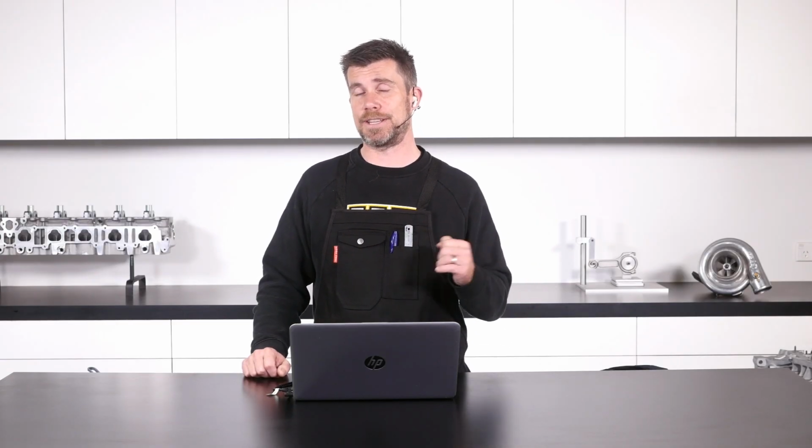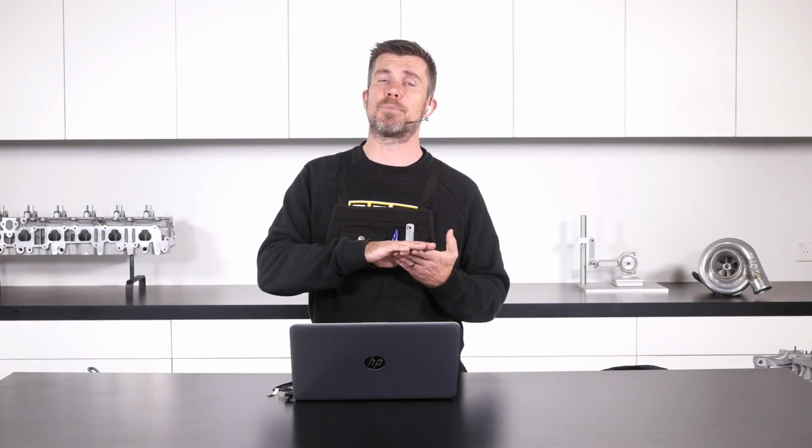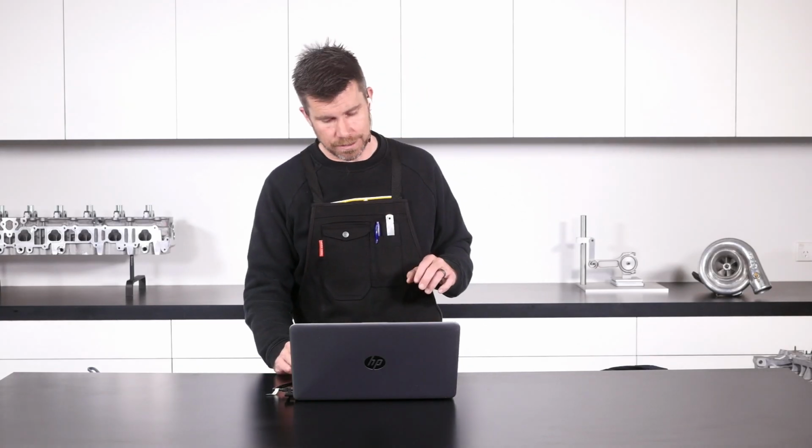So our relationship, if we looked at that as the car goes up Pikes Peak from the start line to the finish line, is that the exhaust manifold pressure just continually will increase, which starts to strangle the flow out of the engine. So hopefully when you start looking at the overall picture as opposed to just the inlet manifold pressure, you can start to see that we're still not going to end up with the same engine power at the start of the hill climb as what we end up with going across the finish line.